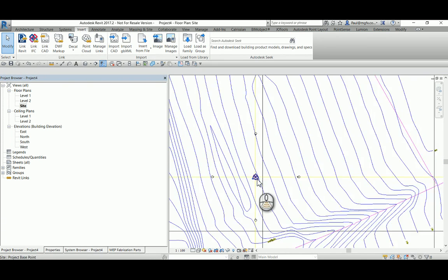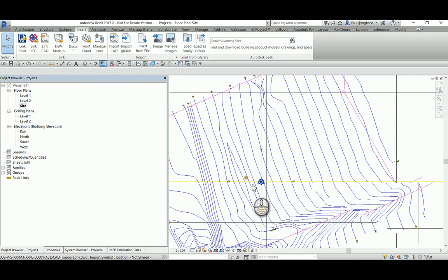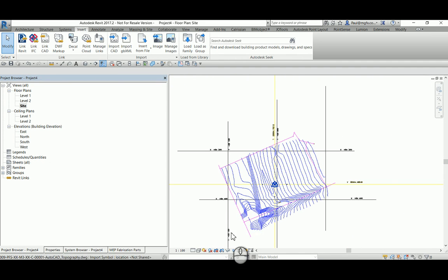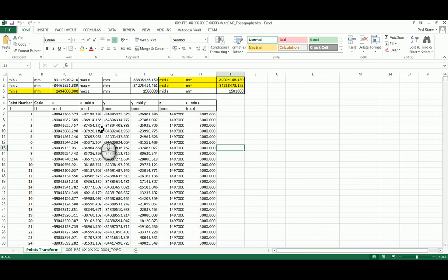All right. So how did we get to these yellow lines? I drew these yellow lines up in CAD, and I got it in the following way. I'm now going to switch over into Excel and just demonstrate quickly what was done. So initially I created a point extraction giving me the X values as highlighted on the screen over here. There's quite a lot of them. And then there's the Y values, and the Z values.